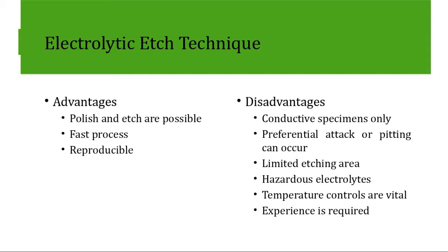Now that's pretty neat because especially if you're going to do any type of comparative analysis between, let's say, vendor A versus vendor B that both have a 4140 sample, and your client is trying to identify, well, they're claimed to both have the same mechanical properties. I just want to make sure that they're both the same chemically and microstructurally.